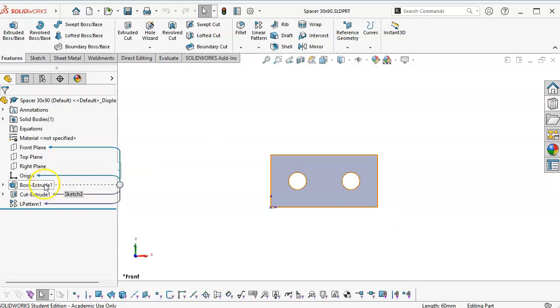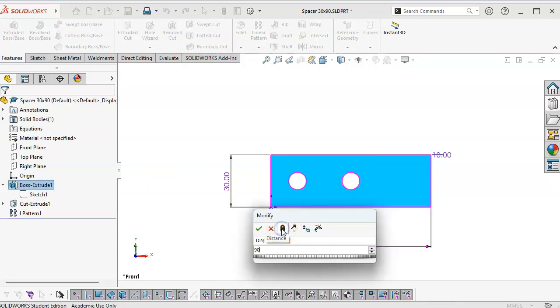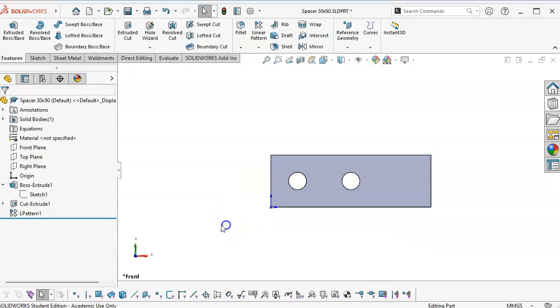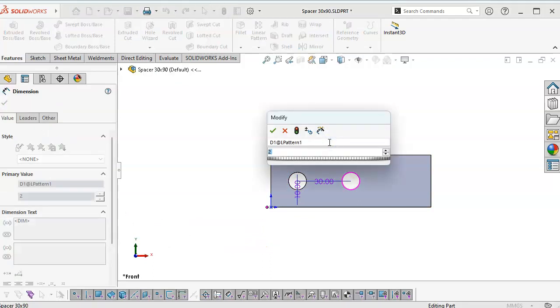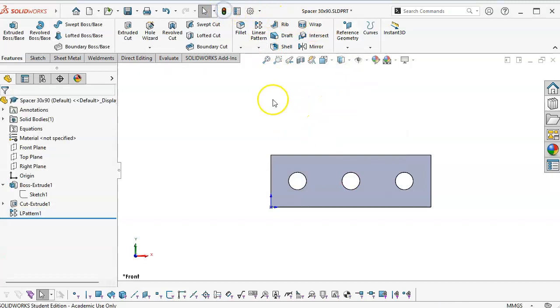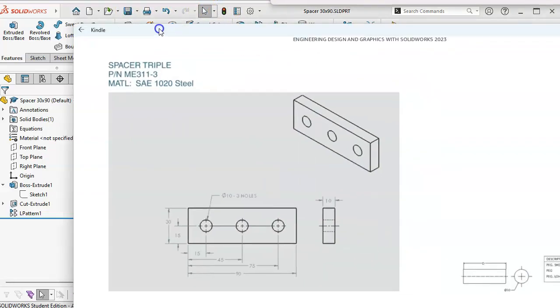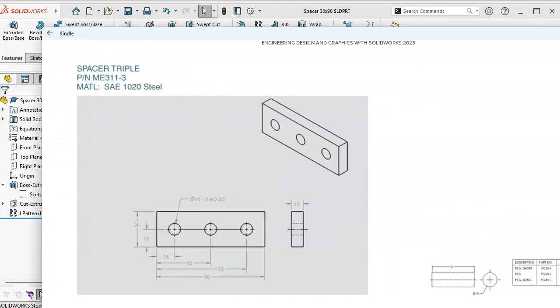All right, so now we're going to do the test. I go from 60 to 90, and if I do happen to remember to hit rebuild, it updates immediately. And then when I look at my pattern, I find the 2, and I tell it to go to 3 and rebuild. Since that was an instance count, we can save that. All right, so I'll see if I can do this without messing up my screens.